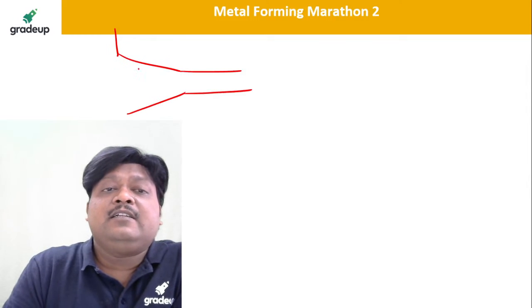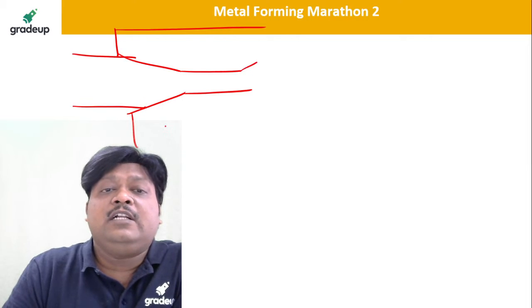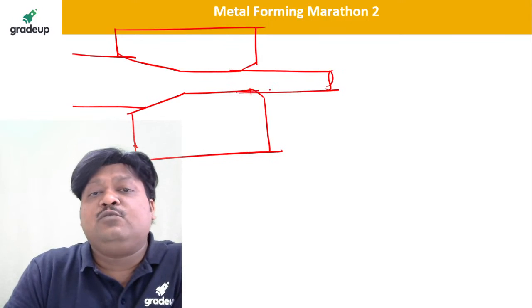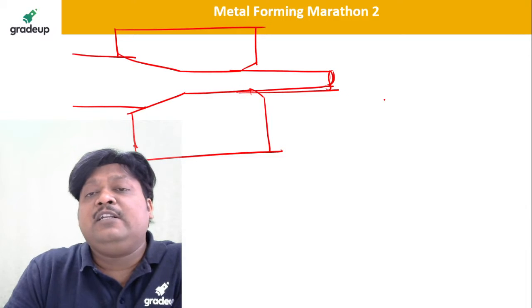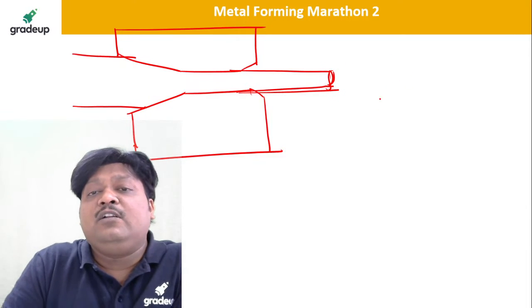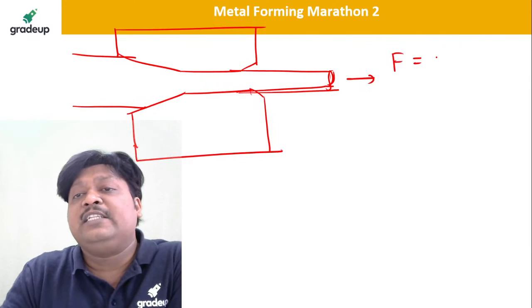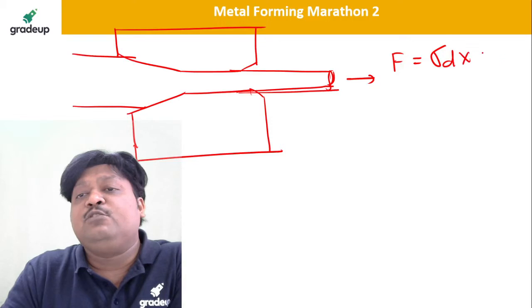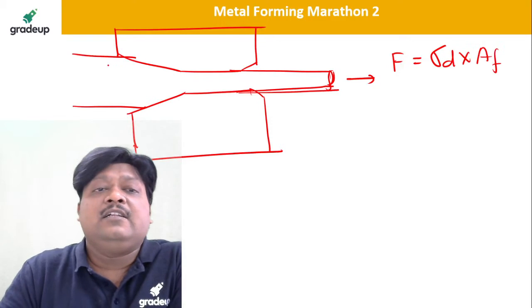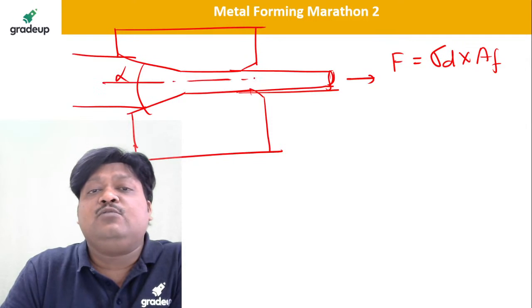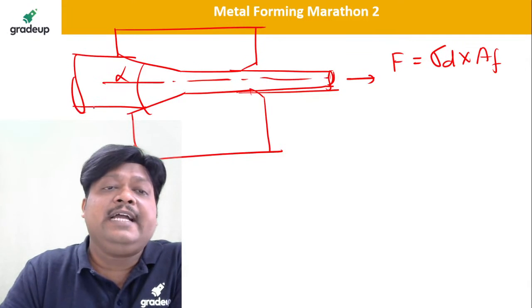Input is a rod, of course with circular cross section, and output, dear students, is coming as a wire, you know very well. And we are pulling this wire, and winding this wire on the roll. This pulling force in the wire drawing operation is nothing but the drawing stress into final area, right? And of course this is the cone angle, dear students, for this die, right?